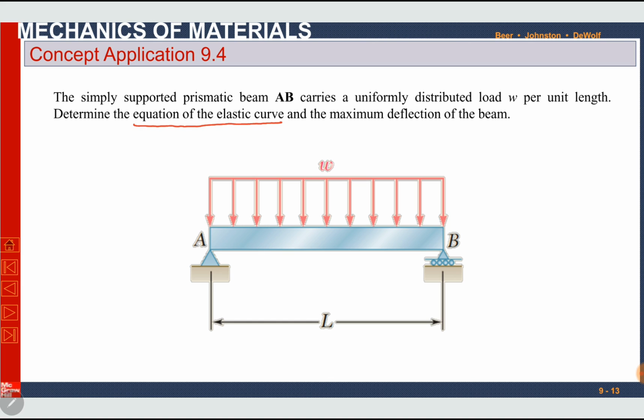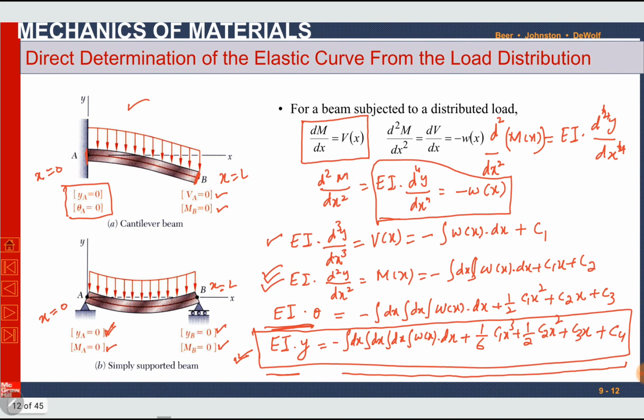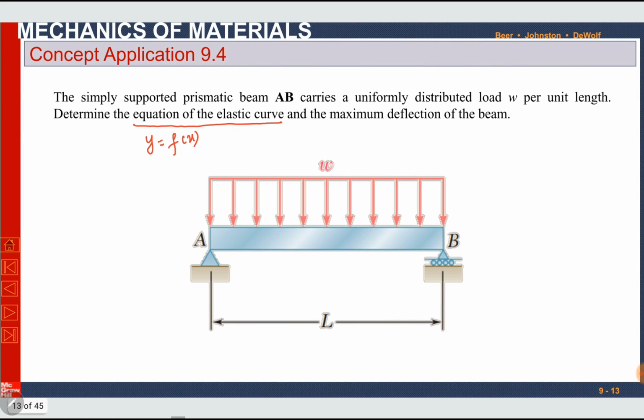The equation of the elastic curve will always be asked in almost all of these problems in this chapter. Equation of elastic curve is the equation of y as a function of x. So we have to determine this expression. We have already derived a general expression here, so we will find this expression. Okay, then determine the maximum deflection of the beam. Maximum deflection is y maximum.